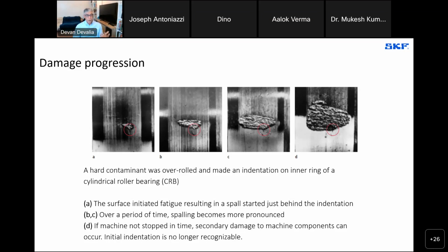Or even monitoring lubrication conditions. Sampling oil and grease regularly might give us an idea that there are wear particles from the bearing, and trigger us to say, hey, we need to pull this bearing and have a look at what's going on in there.